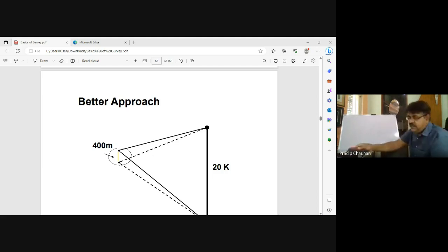So say for example, there is a length where some projects are there in a zone. This is the local side and this is the alignment of the road or rail, whatever. Say this is the ROW, or strip, which is required to collect all this data. For example, this is say 60 meter in length. So I should cover at least 30 meter on either side of the center line of my road to design a road, to prepare a DPR, detailed project report thereof.